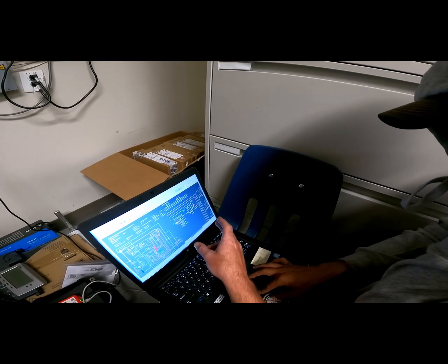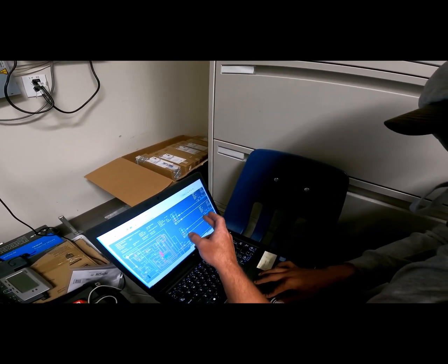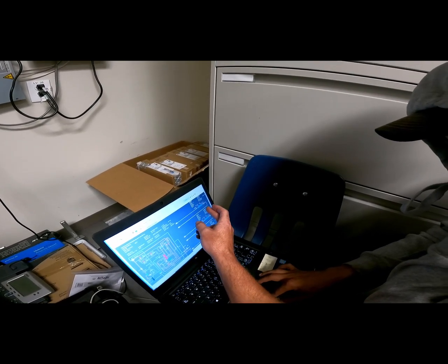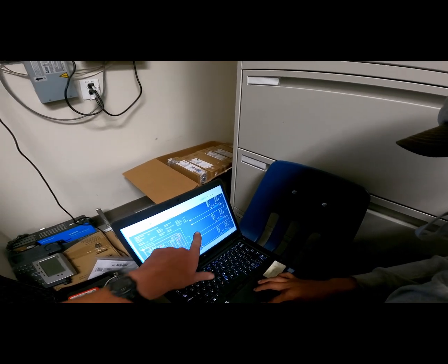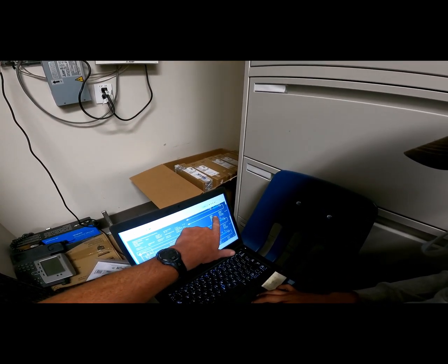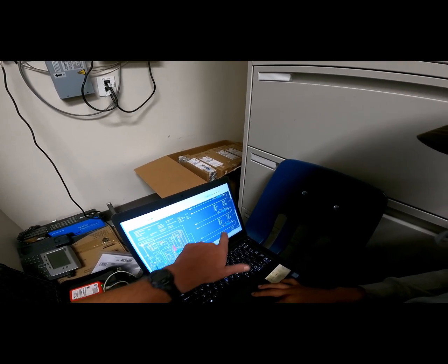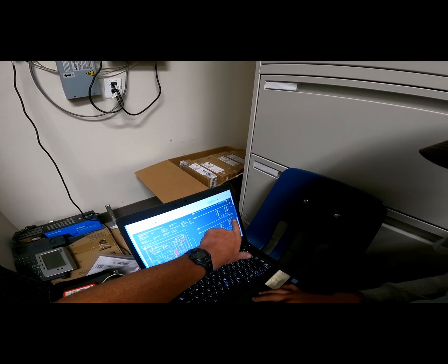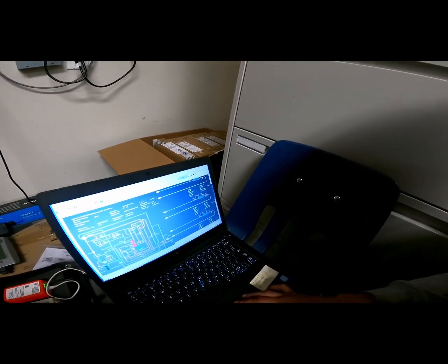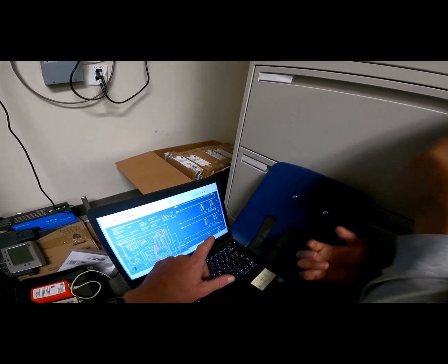Scroll this bar over a little bit and look past the branch controller, and you can see all the indoor coils in here. Here's an indoor coil, there's an indoor coil, there's an indoor coil. What you see here is liquid refrigerant. It's not flowing on that one unit. That's the one that's still in standby. But let's look at this one. You got liquid refrigerant coming in, going through a metering device. You see how it says LI? Mm-hmm. That is linear expansion valve.